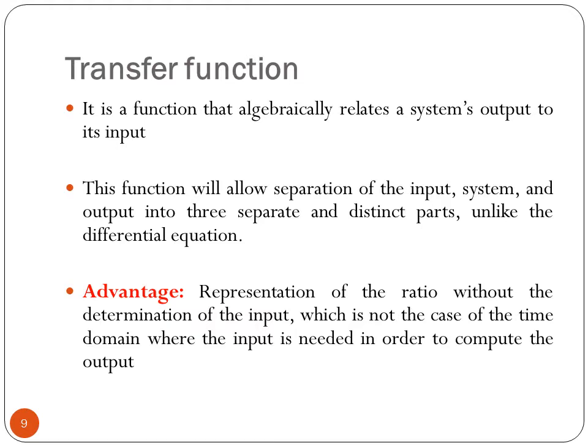The transfer function is the function that algebraically relates a system's output to its input. We have a relation between the output and the input. As is clear, it is one output and one input. So a transfer function is a link between one input and one output only. If we have more than one input, we'll see later on what to do.